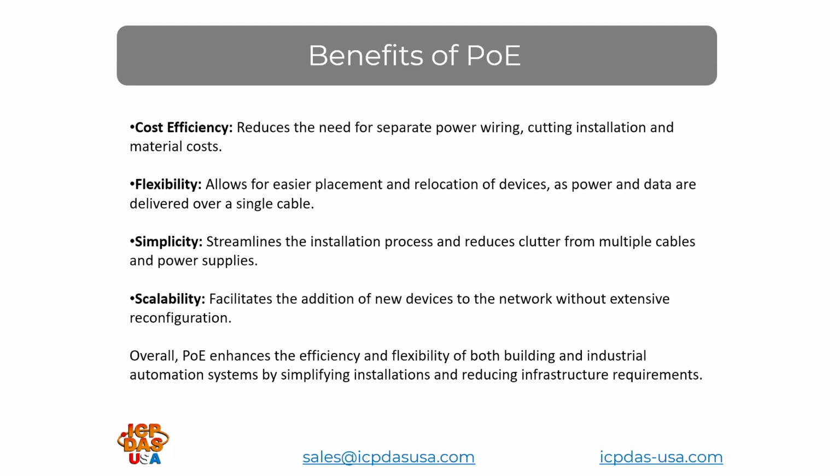Scalability, it's very easy to add the infrastructure for an Ethernet network because you can use off-the-shelf products along with the PoE-enabled switches and the PoE devices. Overall, this enhances the flexibility of PoE in building automation, industrial automation, and many, many other applications. It can be something as simple as adding an IP camera that you want to use for security, or it could be something as complex as adding an automated network for controlling an assembly line.